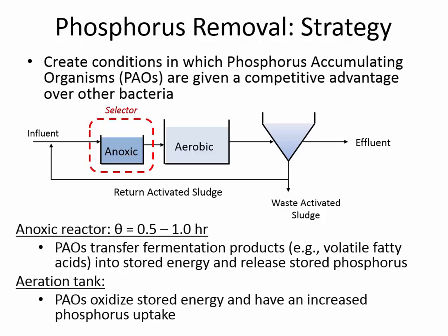I don't know what we'll see at the Huntington plant, but I don't remember ever seeing phosphorus removal at any of the plants that I've been to. How do they handle it at those plants, or is it just not needed? It's usually just that the phosphorus concentration is already low enough that they're going to be able to hit their limit, or that there's a minor amount of phosphorus removal in just a normal aerobic basin.